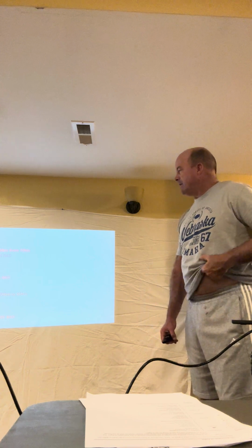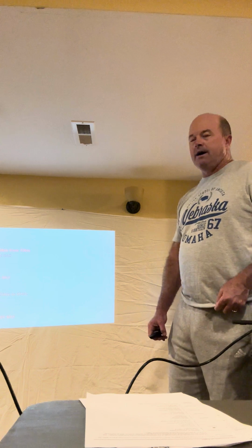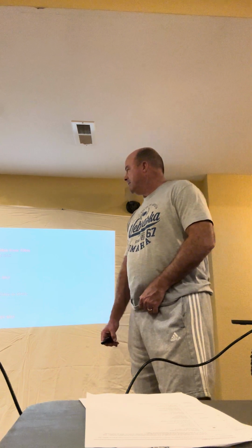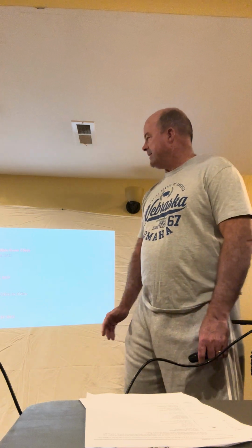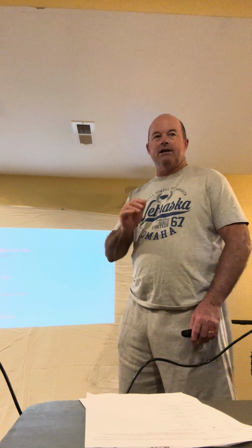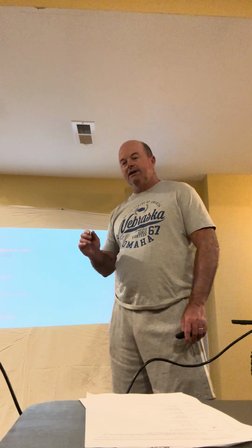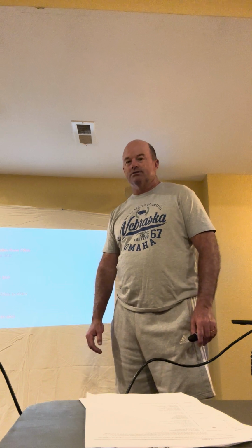So now the stall speed decreases, right? So that's pretty cool. It goes from 72 to 65 knots on a 172. You have less tail drag, which is good, right? And then you got faster speeds, which is good. In fact, some pilots will load up the back of the airplane and give themselves an aft CG in order to have a faster airplane, which is not very smart, because here's what happens.